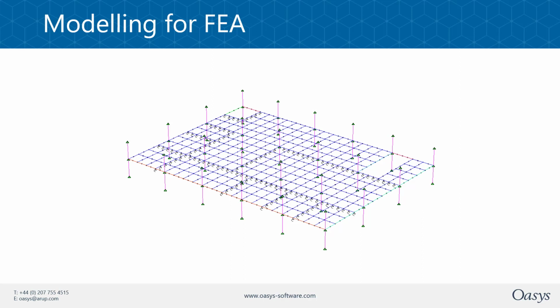You can include the stiffness of partitions on the floors as nodal frame stiffnesses, or maybe explicitly model them as shell or plane stress elements. Alternatively, you can just pin the nodes in place. Each design guide has its own recommendations.